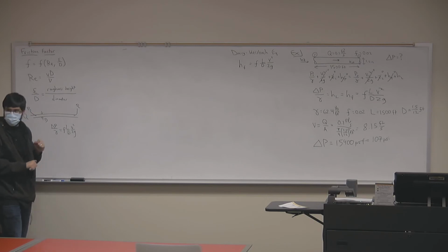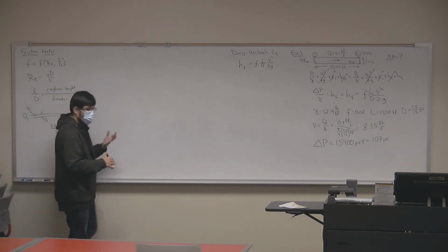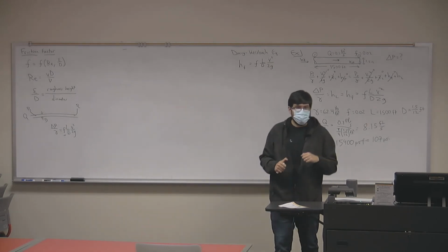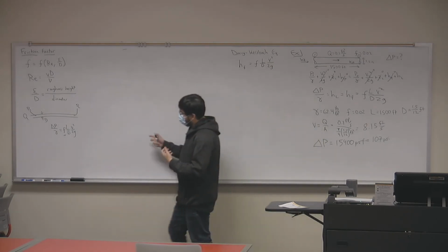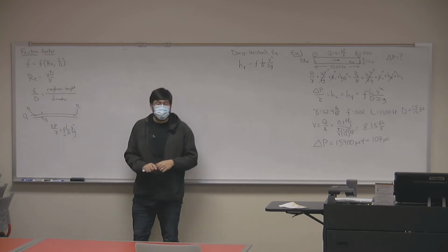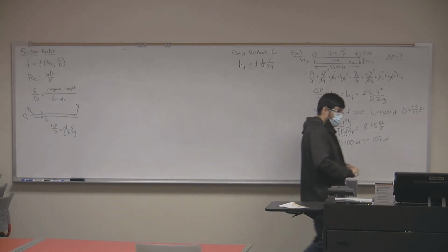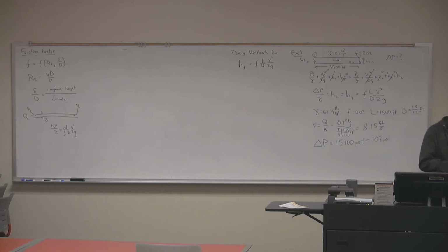The friction factor, right? So we do that experiment in order to find the friction factor for this pipe. Now the reason we do that is because there is no analytical way of saying, hey, this is my friction factor, here's the equation that proves it. Instead, we resort to these empirical or experimental methods to determine the friction factor.